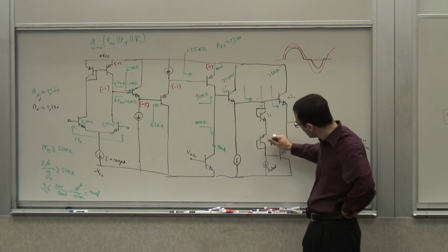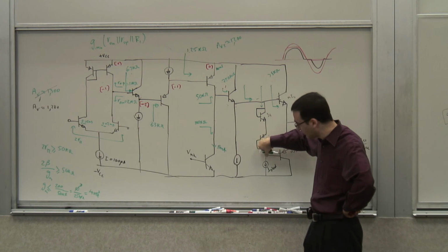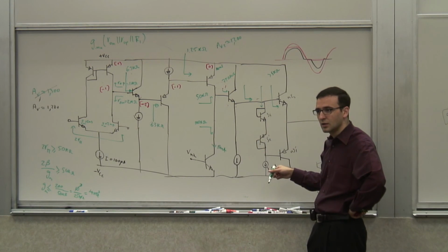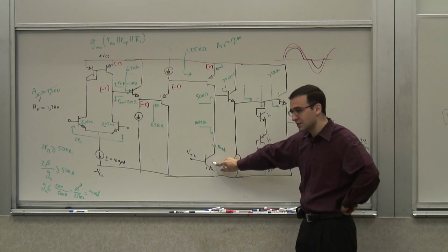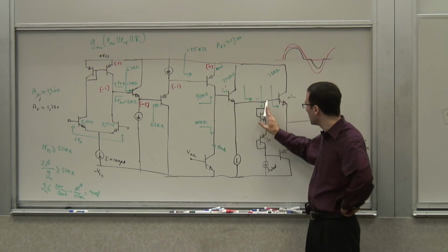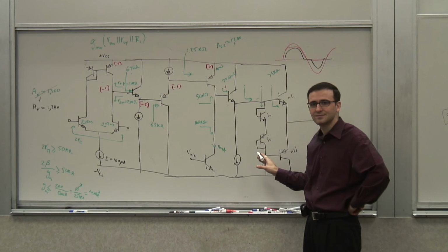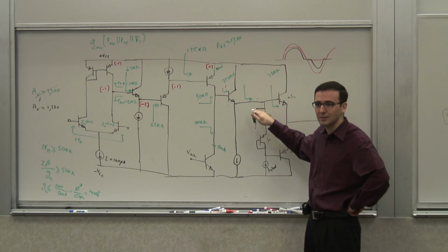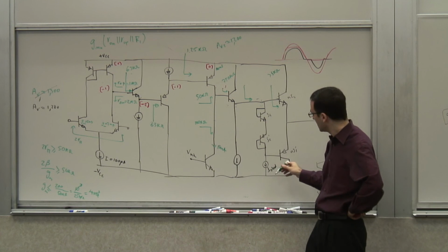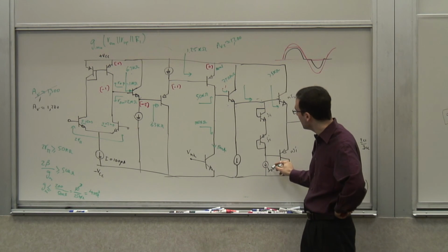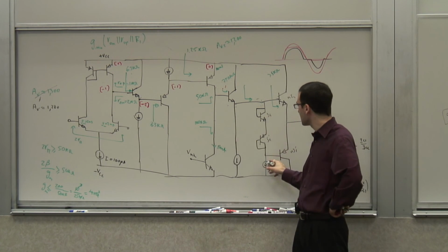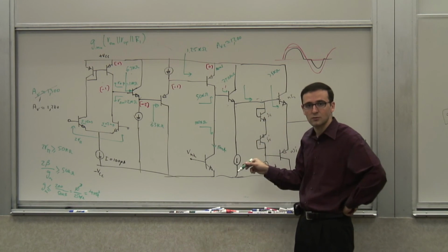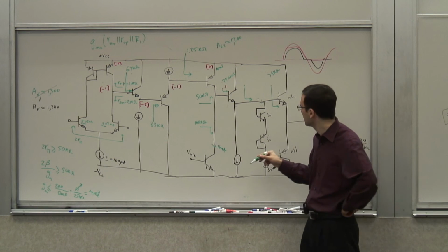What is the impedance you see looking down here? Well, this part is infinity, or very large, because it's off. What is this? If it's made out of the transistor, it's Ro. So it's quite a large impedance. So I don't need to worry about that too much. It's the Ro kind of thing. It depends on the current levels, of course. So let's say if this were run at 1 milliamp, this would be about 100 kiloohms. So it's 100 kiloohms plus 25 plus 25,